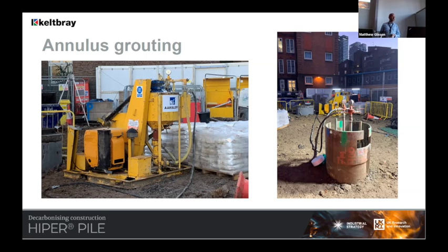Good questions. Okay. So the first one, the EFC itself as a binder is a much stronger binder. So it actually gives you a slightly denser and less porous concrete. So in and of itself, it's a more durable matrix. Particularly when you're looking in the ground in terms of the sulfate resistance. What do you do when you get to a DC4? You just keep adding more and more GGBS, whereas the earth-friendly concrete is equivalent to a DC5, which is what you don't currently have.